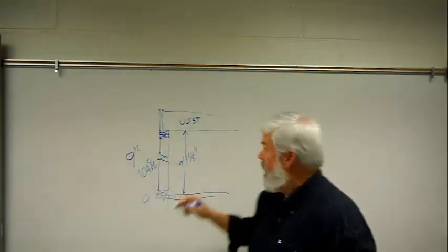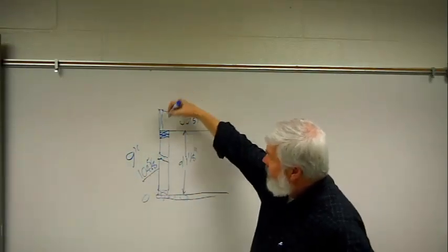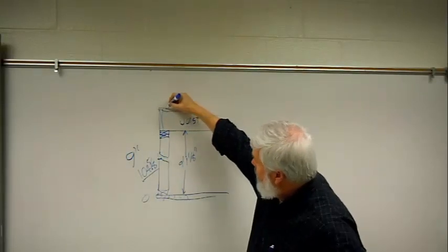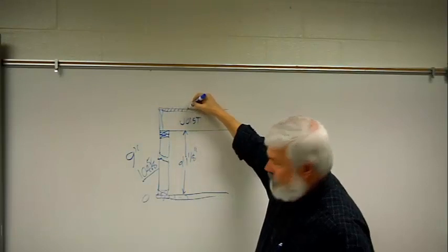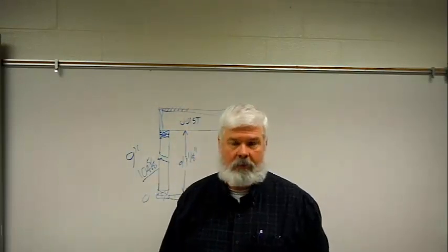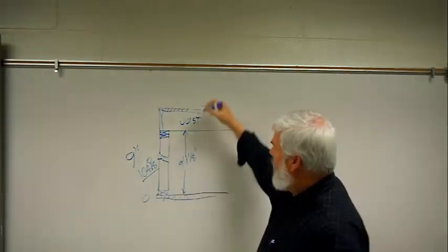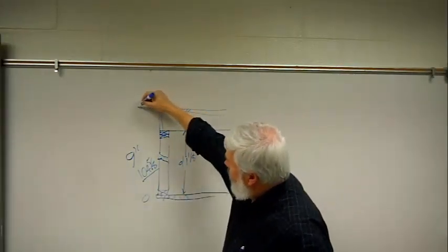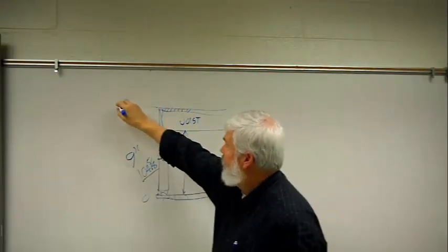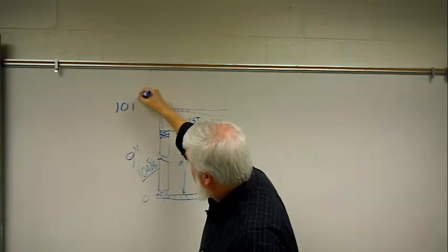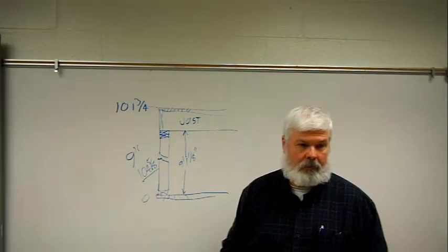The rooms feel bigger. So the stud is 104 5/8, and so if you add all of this up and you put 3/4 inch plywood, which is not really 3/4 inches, how much is it? 23, 23, 32nds. Yeah. You get up to a level here, which I have on your instructions for your template, of 10 feet, 1 3/4 inches. And that all adds up.